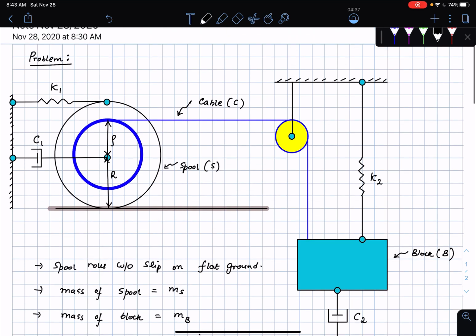Okay, so whenever I look at a problem like this, I say, okay, there's spool kinematics involved. Then there's a cable pulley system, so there is cable and pulley kinematics involved. Then after I'm done with that, I start off by finding the number of degrees of freedom involved. Once I have that, I realize you need to start off with the sign convention for the coordinate systems, or the degrees of freedom. And once I do that, free body diagrams, kinetic diagrams, and we are home and dry.